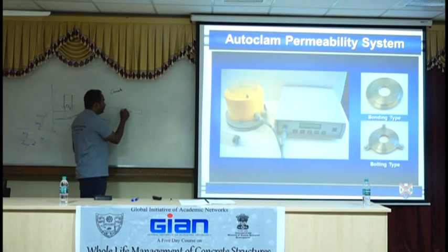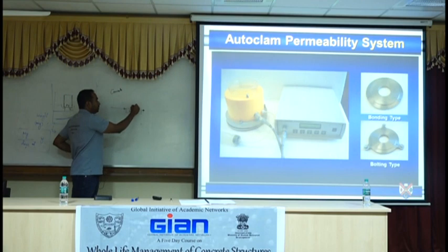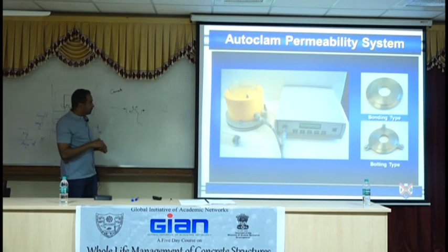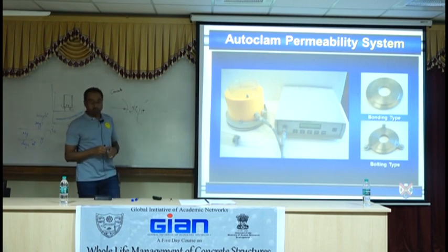When we manage to do that, this is the fixing bolt. So it's fixed onto the surface. It then will let the moisture go into the concrete. If we have a way of measuring the water that's leaving, we then get the rate. It's quite easy. The tricky part is, where does it go? It goes everywhere. Okay? But that's a bit of mathematics.